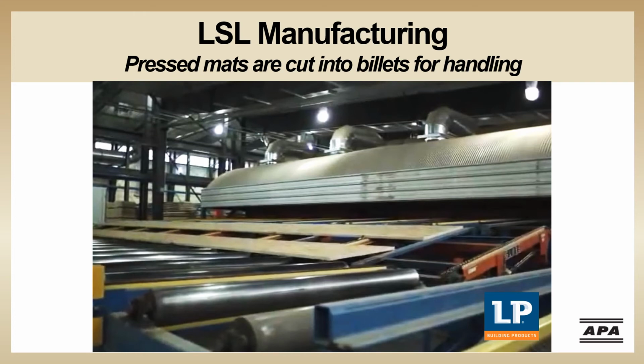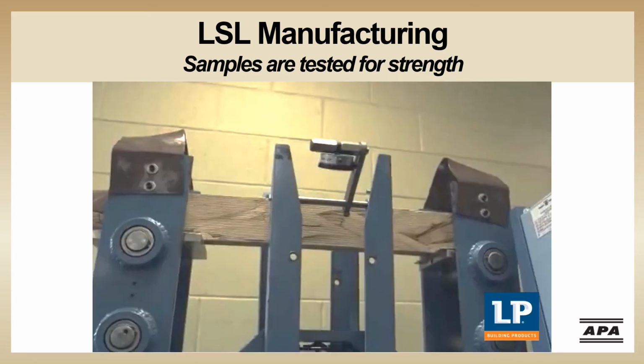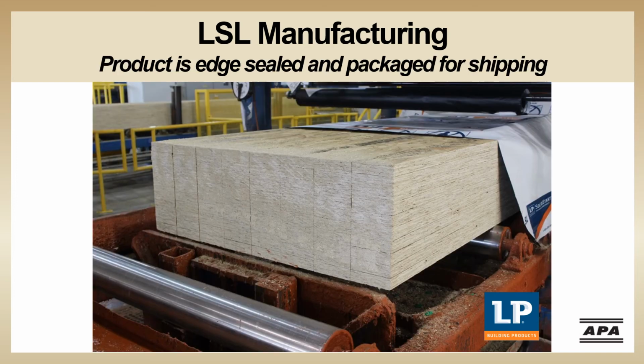The press mats are then cut into billets for handling. There are quality control checks done in the mill to ensure proper glue bond. The samples are also tested for strength. Then the billets are cut into custom sizes with a rip saw. The rip members are then dimensionally checked to ensure uniformity. In the last step of the process, the product is edge sealed and packaged for shipping.